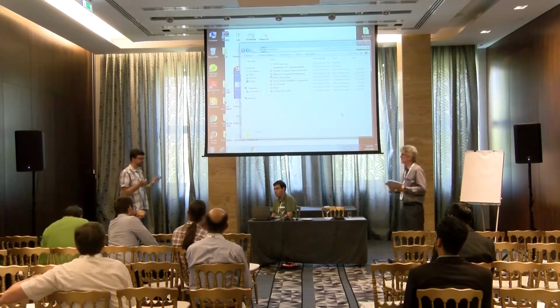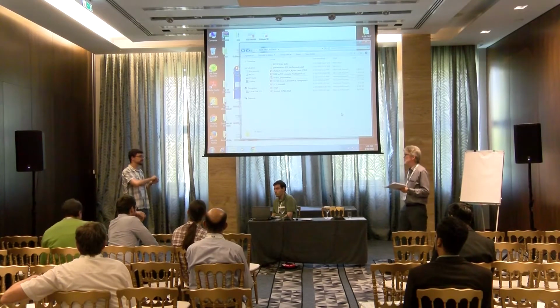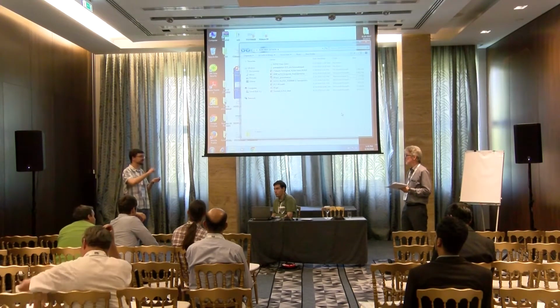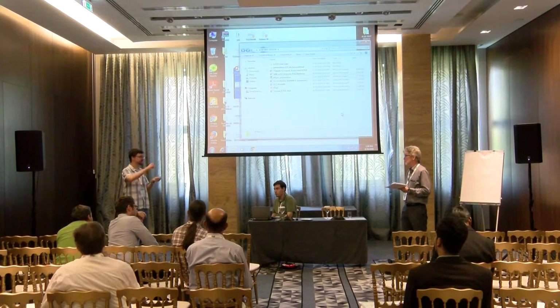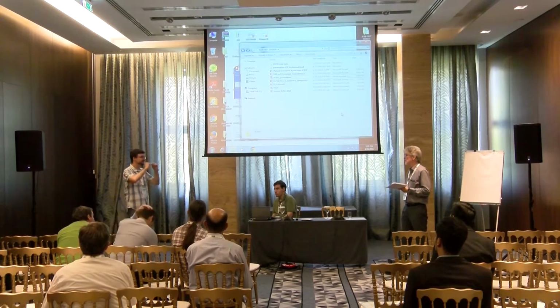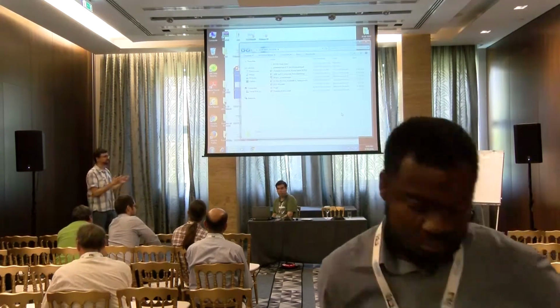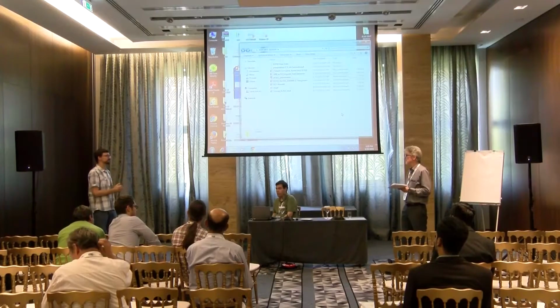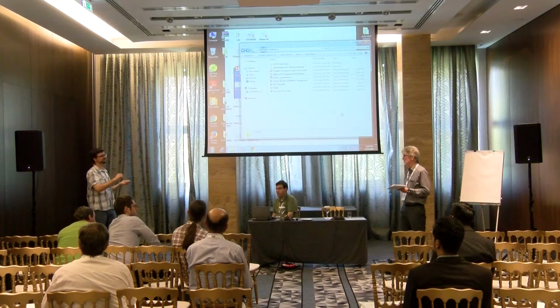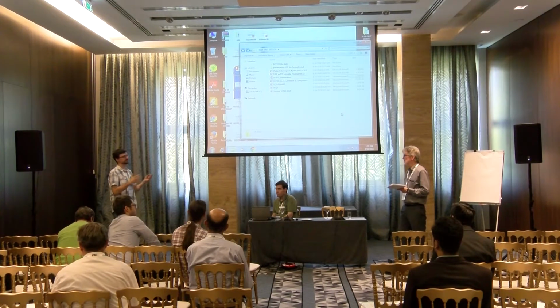Okay, the basic method is micromechanical exfoliation, when you peel it off from graphite. But you can make it thinner and thinner if you repeat this procedure until you make it single layer. This is the procedure which was applied by Novoselov and Geim, who were then awarded the Nobel Prize. They call it the Scotch tape method. It's very easy. As I said, it is not for realistic applications, but for research, for labs, it works.